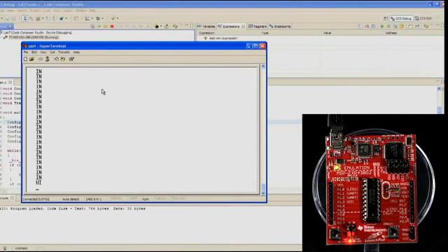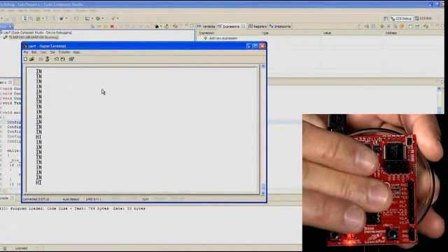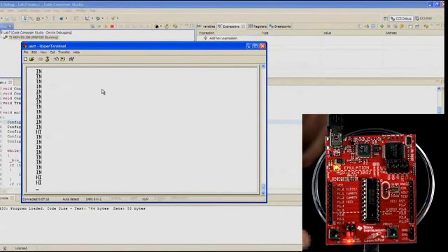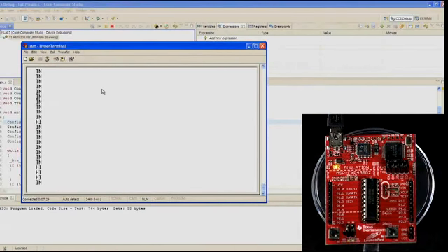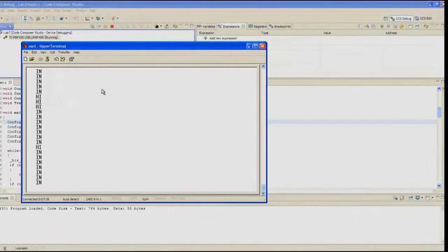So we're going to exercise the code. We're going to reach over here and warm up the device. I'll put my finger on the top of the device. And at some point it should say HI. You'll also notice that the red LED is on. If we can get the device to cool down, it will say LO. In the middle, both LEDs are off, so now we're back to IN. We're right at the edge there where it's going between one and the next. It may be hard to get it to cool down. Remember, the reference temperature was taken when the code was first run.